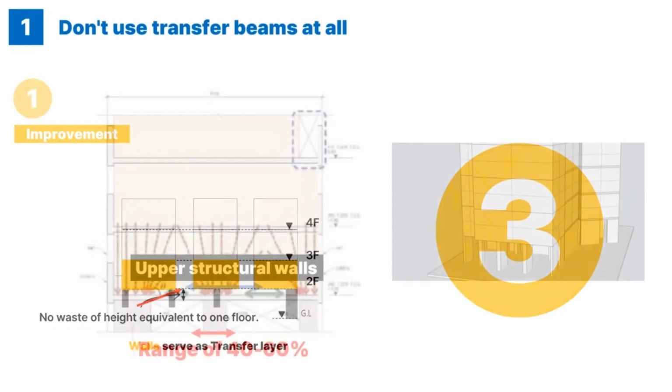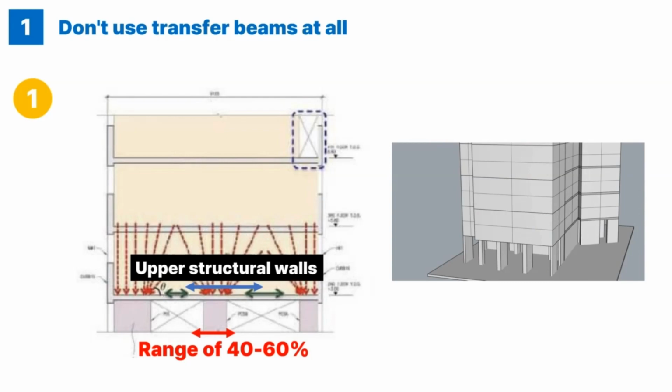First, to prevent additional stress due to eccentricity, or excessive bearing stress between the structure walls and columns, the size of the pilotis columns is assumed within the range of 40 to 60% of the length of the upper structure walls.